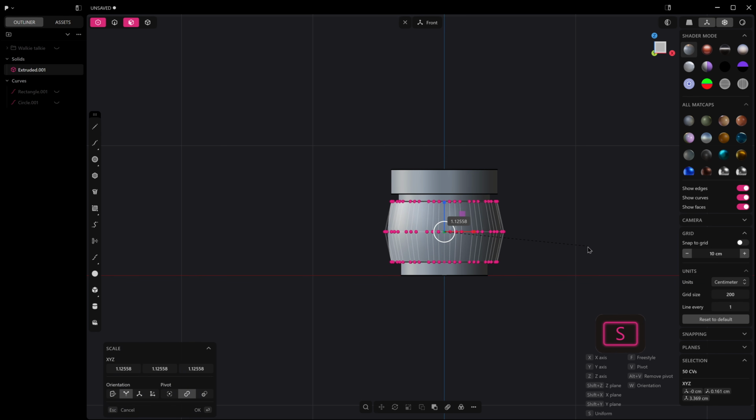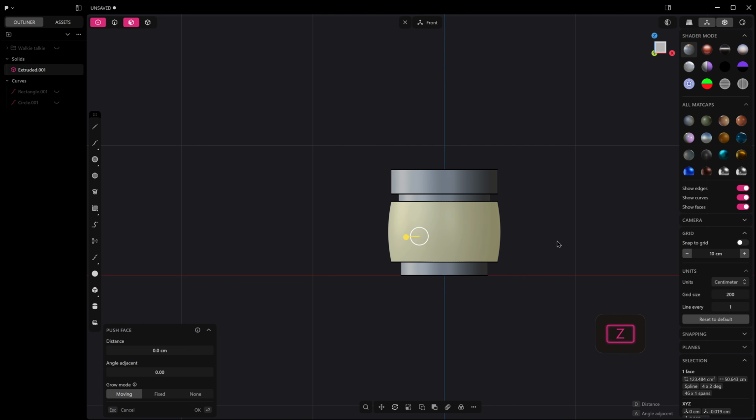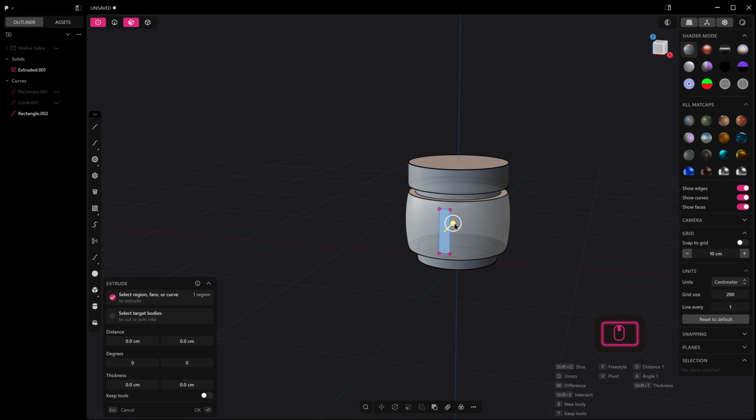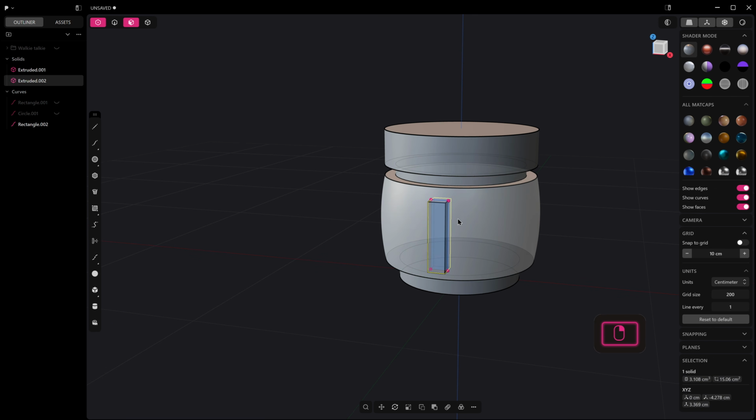Okay, and we're going to kind of do a little bit of everything we've learned up until this point here. Okay, so what I'm going to do is press Z to toggle my points. Let's take a rectangle in the center here, press C to make it a center rectangle. I'm going to bring this out and press tab, but just a wee bit.